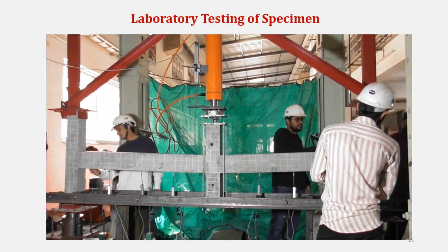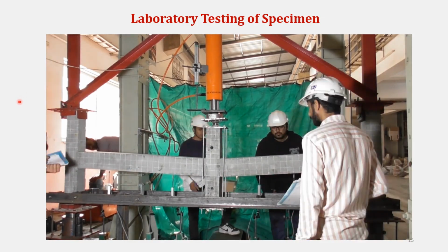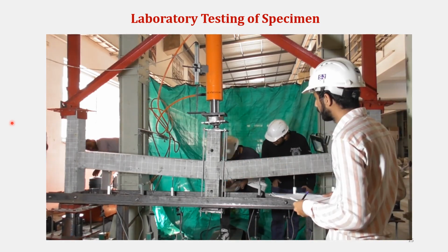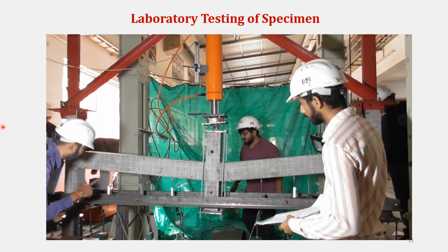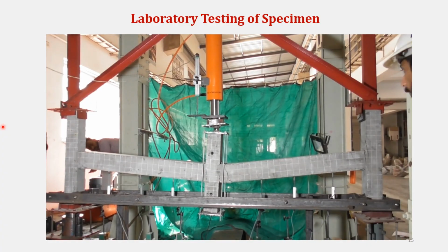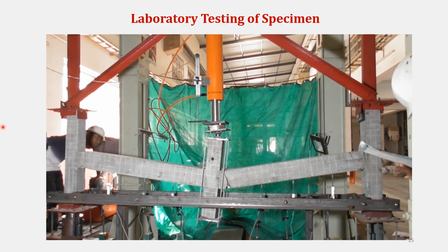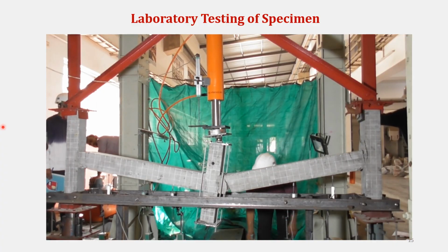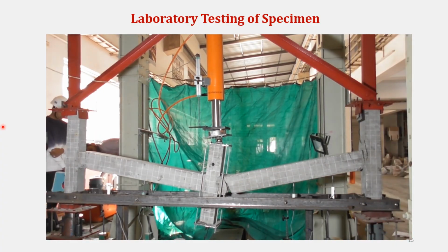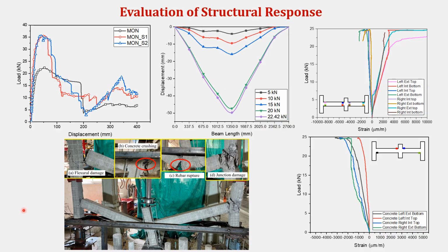This is an actual photograph of the specimen arranged in the setup before loading. Here is a small footage of actual laboratory testing of the specimen. Of course, this is a small footage of a fast-forwarded video. Load cells, LVDTs, and electrical resistance strain gauges are used to measure load, deflection, and strain values respectively. Response of all the quantities is captured in a laptop through a data acquisition system. The response is evaluated in terms of load deflection behavior, deflection profile of the specimen, strain values, as well as failure characteristics. Other parameters such as stiffness, ductility, and energy absorption capacity are also calculated based on the load deflection response. The sample graphs of different response parameters obtained through post-processing are shown here.